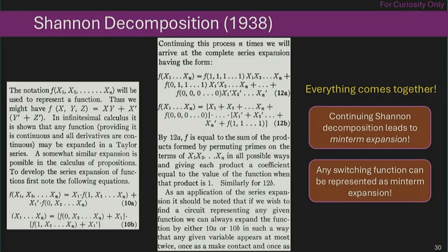And you see, you can apply decomposition on one variable. You can apply it on two variables, like in that 4-to-1 mux. We use 2 selection signals. And you can also do that on essentially all the variables. At that point, you get a minterm expansion. And because we know minterm expansion can represent any Boolean function, we get to prove that we can use a mux to build any function.